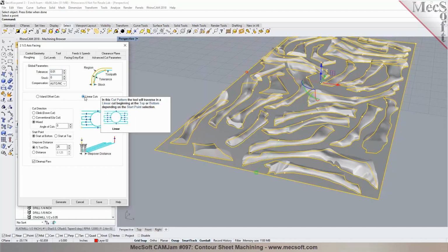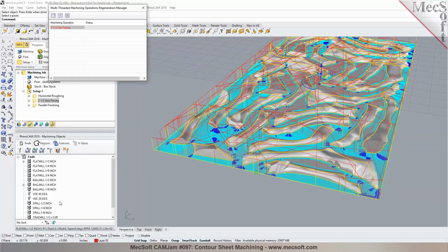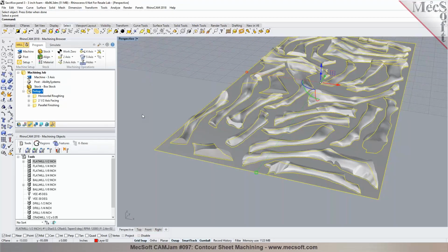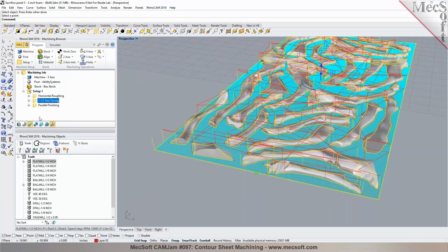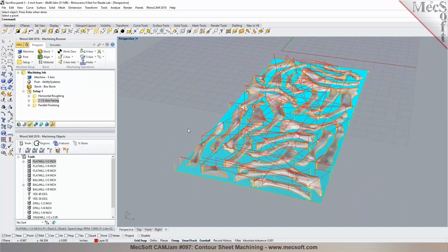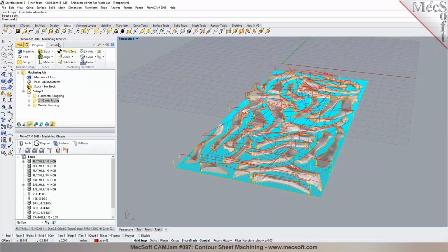Well, it'll indicate and it'll mark those collision areas for you. It is not going to stop it. You would have to specify like a Z containment to stop it. You can separate them into different areas, and then you can say on these areas you don't want to cut past 2 inches, or you want to leave 2 inches from the floor. So you can basically break them up into different areas. But you would have to pick those areas yourself, right? That is correct.